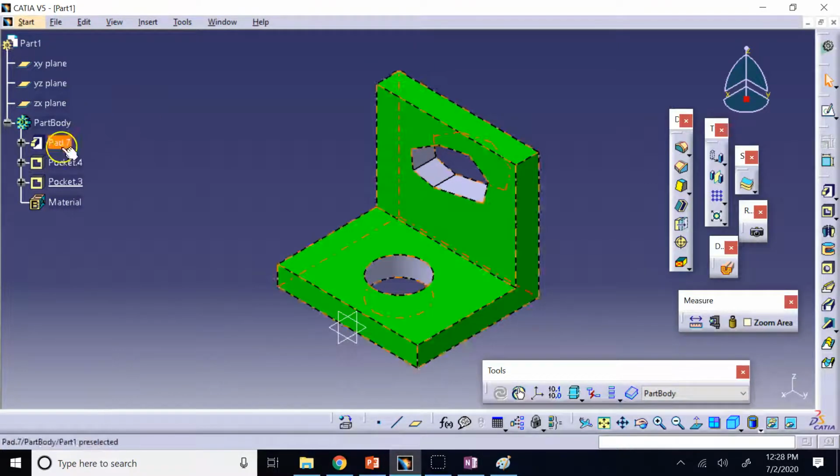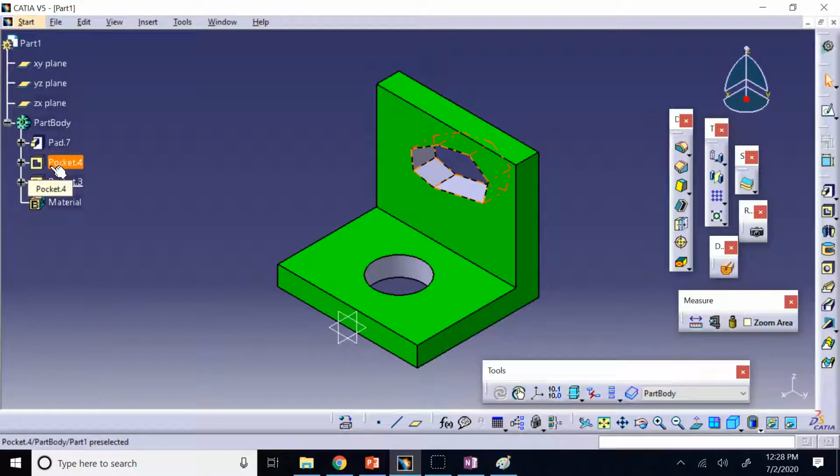What I mean is, you created, let's say, a loft using 2 profiles. After you created the loft, later on you have some new sketch which you now want to use as a guide to the loft, okay? So you double click on the loft and say, in the guide window, I want to also specify this sketch as the guide for this loft. CATIA won't accept it. Why? Because this sketch that you made for the guide was created after that 3D loft.